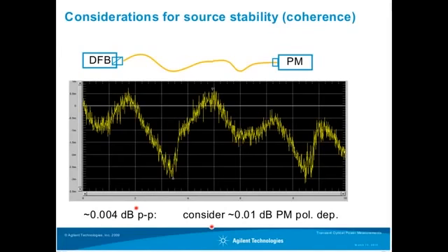And this brings us to the second case of what could be a source of instability in a signal, which is polarization. These are polarized light sources. We're going through single-mode fiber, which means the state of polarization along the length of the fiber can change, generally fairly slowly, but it can evolve as the fiber moves. If there are any vibrations in the room, air movement, or temperature change, that can all cause usually small but gradual changes in the polarization. But sometimes it's more rapid if there are really vibrations going on.